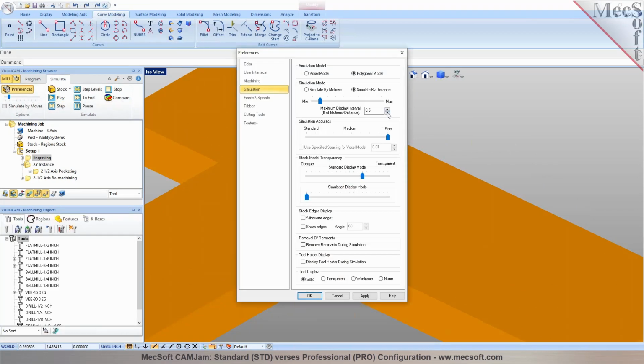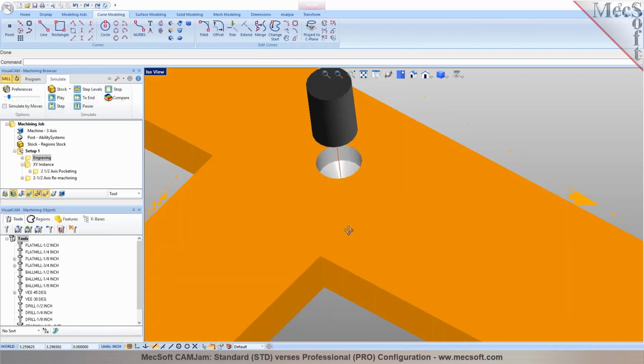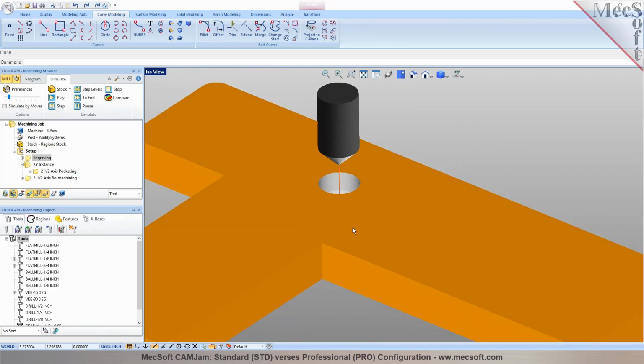Did you notice it, Travis? Well, my issue was after I had drilled and reamed it. Do you want to do a profile cut to clear out the hole? No. It literally just needed a 50 thousandths tall groove milled in about 1/4 inch down into the hole.